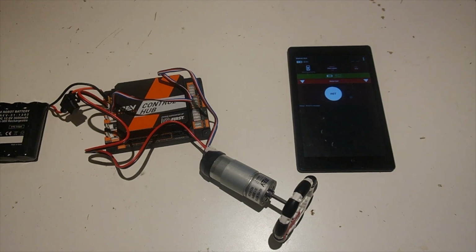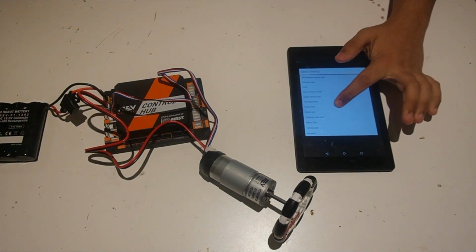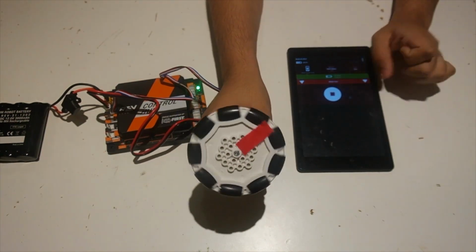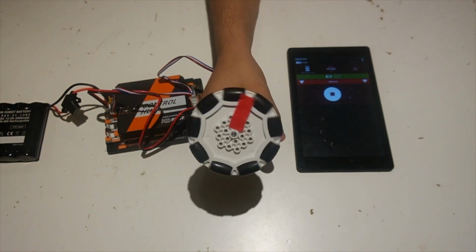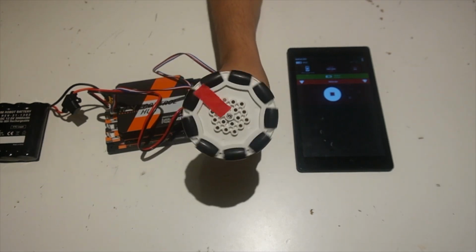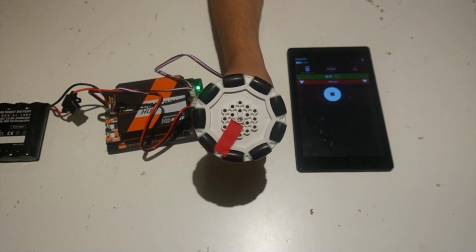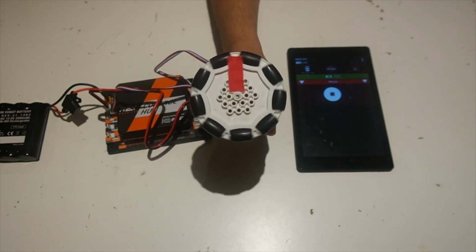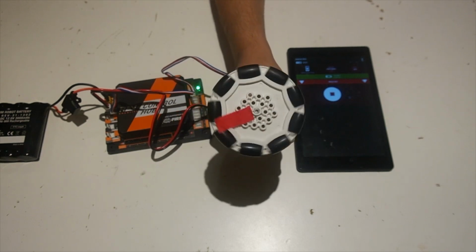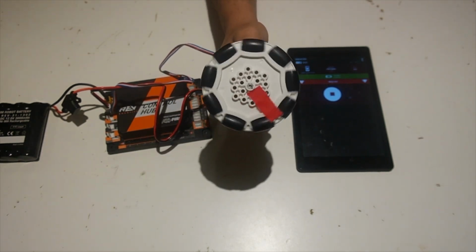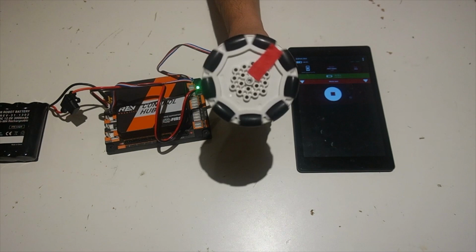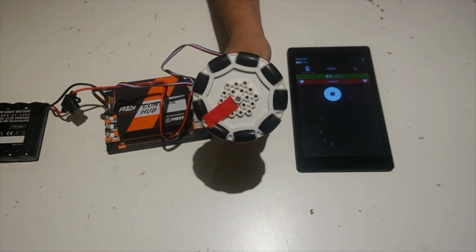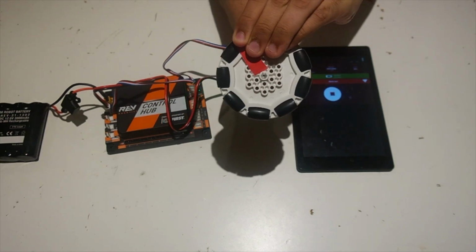Now I have this all out here. I'm going to select motor test, hit init, lift up the motor, and hit play. So what this program was supposed to do is set the motor to rotate at 1 revolution per second, using the encoder to maintain the velocity. You can see that it's doing just that. 1 revolution per second is a bit slower than what it was at full power, so you might want to change this to a higher value, as this is not applying very much power to keep it at 1 revolution per second, and I can easily stop this.